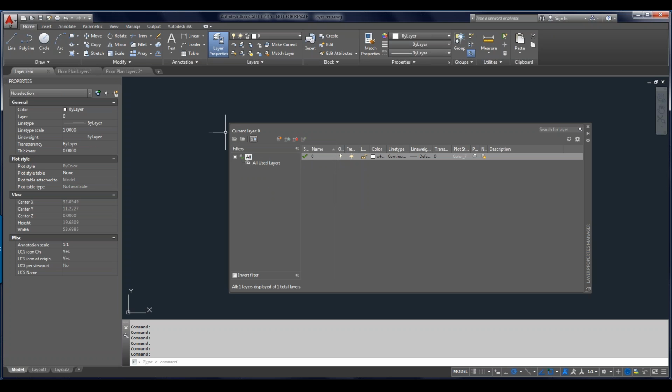We have the Layer States Manager here. All of these have nice tooltips over them, with a quick explanation about them, or you can hit F1 with this dialog box palette active, and it'll take you right into that layer command of the help file. Here we create a new layer. Note the control keys, Alt-N would do that as well in this dialog.